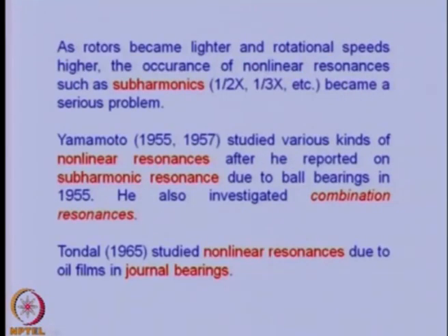As rotors became lighter and rotational speeds higher, the occurrence of nonlinear resonances such as subharmonics of 1/2 x, 1/3 x, etc. became a serious problem. Yamamoto in 1955 and 1957 studied various kinds of nonlinear resonances after he reported on subharmonic resonance due to ball bearings in 1955.